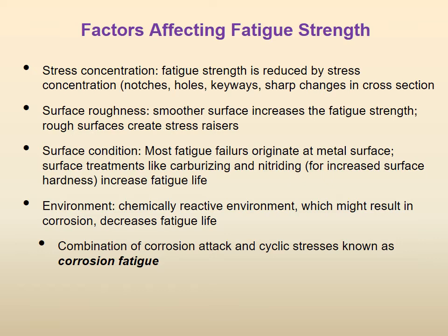Here we have just introduced to you that either small flaws are already there because of primary or secondary manufacturing, or because of this persistent slip band growth. You are applying fatigue loads, and there are slip bands in the material, and there are directional changes. The material starts to deform along the slip band. When it hits a grain boundary, there can be reversal or changes of direction. Those create or initiate the crack. Once the cracks are there, then they will start to grow. That is stage 2.